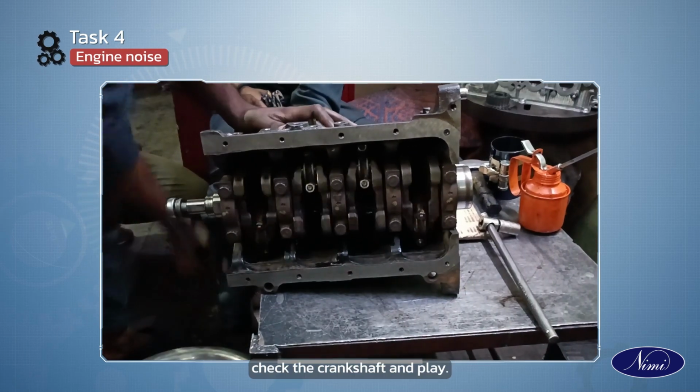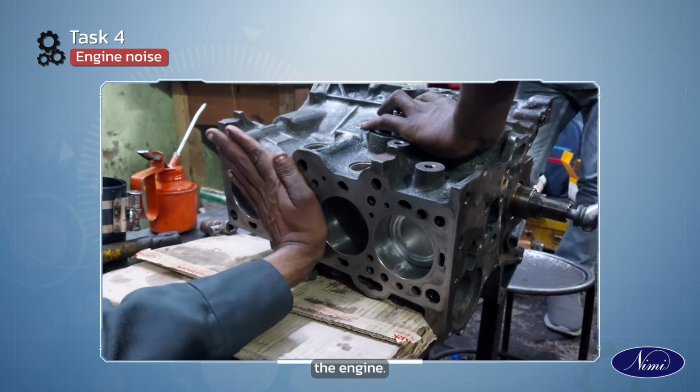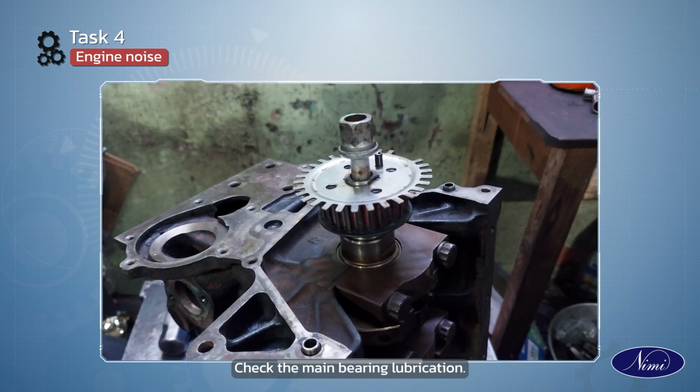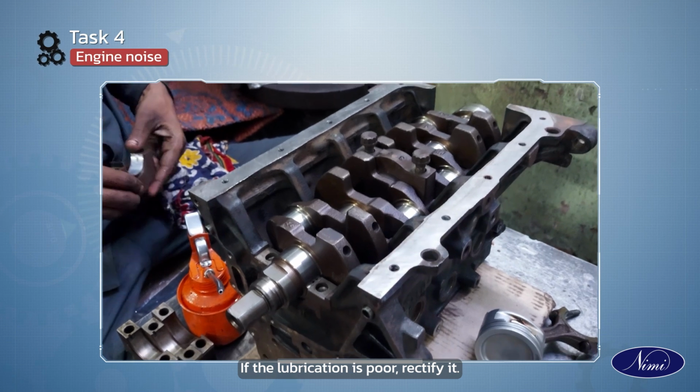Check the crankshaft end play. If the end play is more, overhaul the engine. Check the main bearing lubrication. If the lubrication is poor, rectify it.